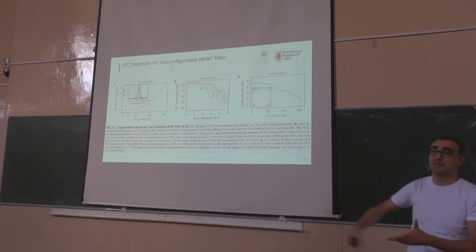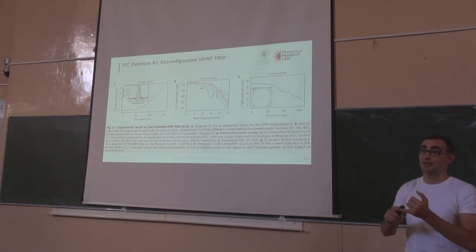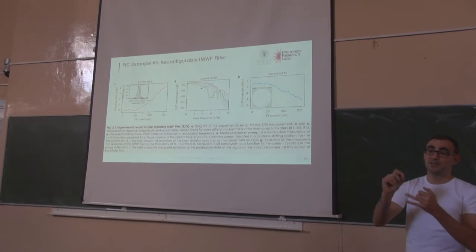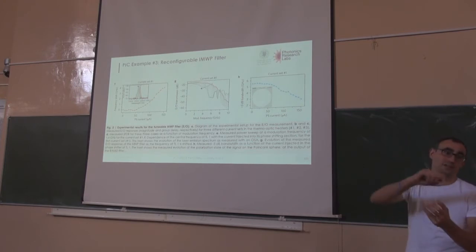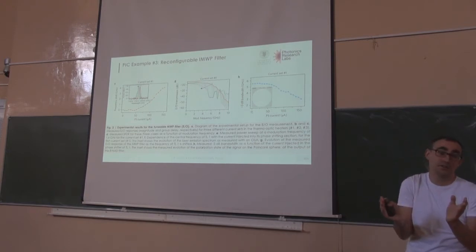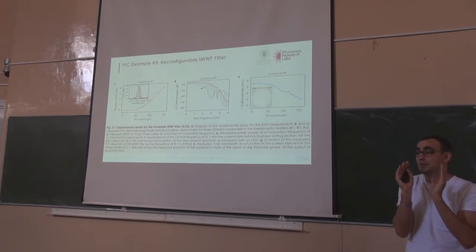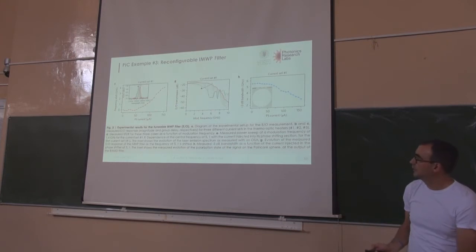Okay? So that is one thing that you need to take into account. Polarization, if you have waveguides that support the 2 polarizations and you have bends, please make sure that either your bends would only support 1 polarization, or that the radius is such that with the sidewall angles, which you cannot avoid because those are done in fabrication, you don't have polarization conversion and rotation and loss. Okay?